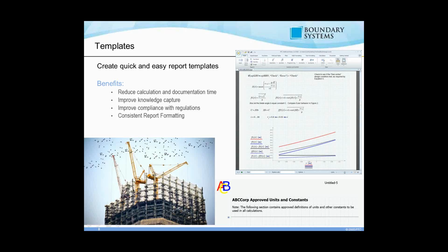So in cases where you have to deliver certain regulatory documents, all of those will have all the different entities you need to furnish that regulatory document. And so, for example, in this case, it could be something as simple as ABC Corp, and in this particular document, you have certain unique units that you have to define yourself, and you can define all of those in the Mathcad worksheet before any calculations start. So that way Mathcad understands what the units conversions are.